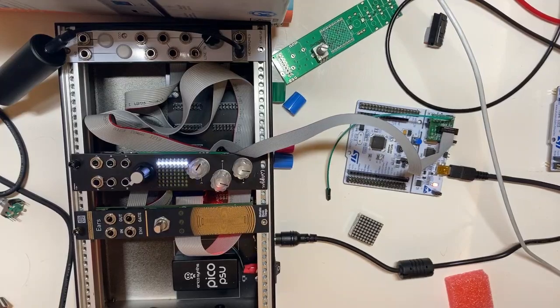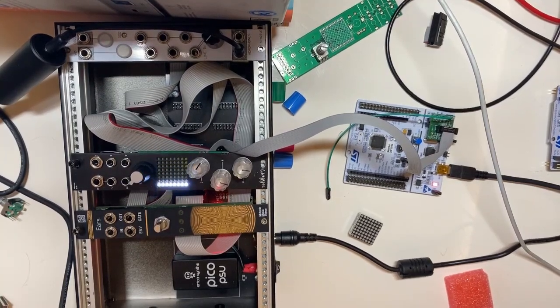And again, this is where this bad boy really shines. Let me just come out of the debugger. Maybe I'll resize this to be a bit bigger. Oh, look at that refresh rate. I mean, seriously. Okay, so PA0, I want that to be an ADC1. The first time I ever did analog to digital on an STM, I had randomly wired my chip to use ADC3, and I could not make DMA work with ADC3, and it turns out it was a code generation bug in this piece of software.